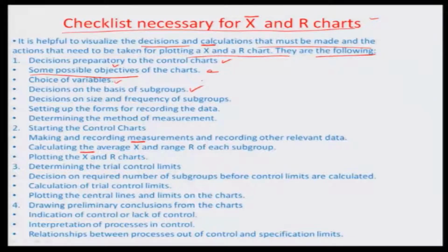And the idea is, once you have started recording some observation, it has to go on for at least a few numbers before you stop recording on that particular event period, and then go for the next event period. So, there are different event periods like this in the whole production shift. It may be a group of 5 observations. These 5 could be, let us say, every second or third item on the production line. So, you are basically recording every third item 5 times, let us say the subgroup size is 5, and then waiting for a few hours, and then again recording after some more hours, the same every third item 5 times again.